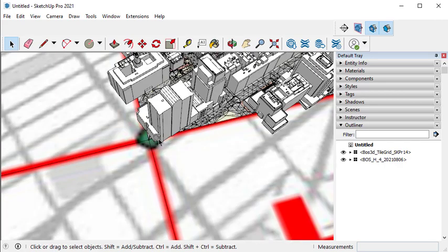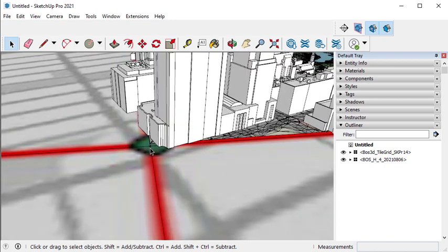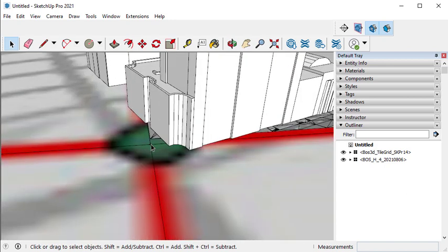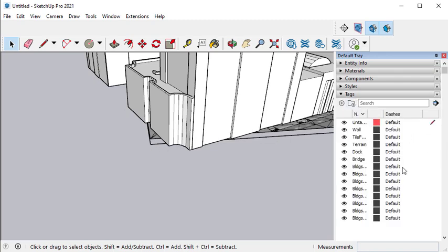One thing that you should check when you're doing these imports is to make sure that your tile grid is properly registered with the model and vice versa. So one way to look at this is to get down to a corner, turn off the tile grid. You can see that each module, each tiled model, has its own tile boundary.